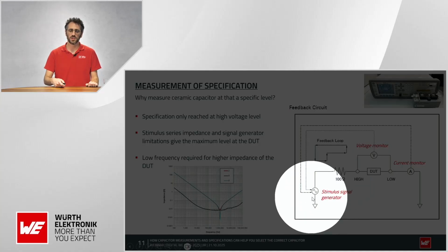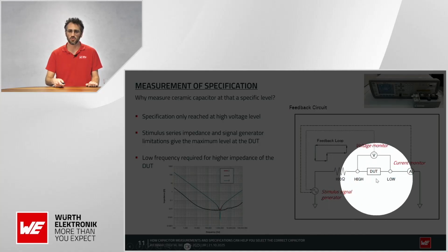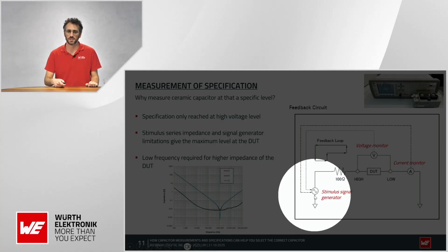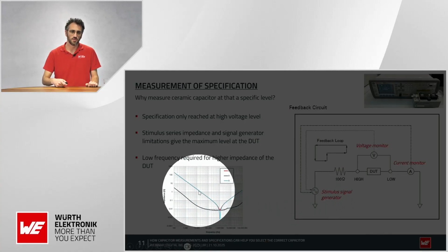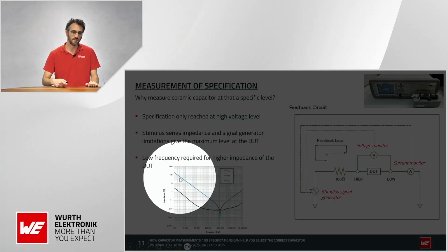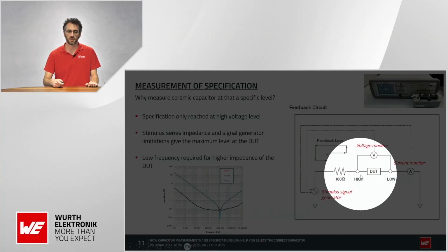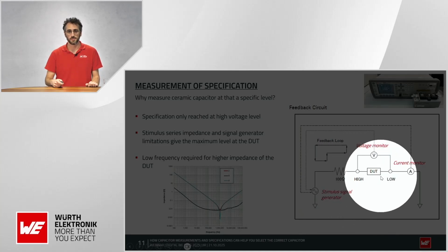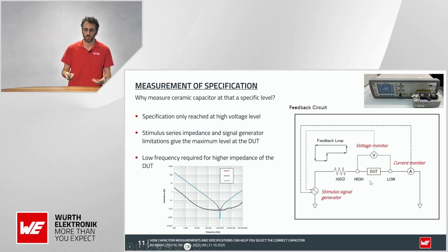It means that we have to generate, to get 1 volt here, maybe 100 to 1000 volts. As you can imagine, this is impossible for this measurement equipment to handle. So we measure at very low frequency, where we have 20 ohms. So it's manageable for the device to compensate for the series resistor. This is the reason why we have this low frequency.